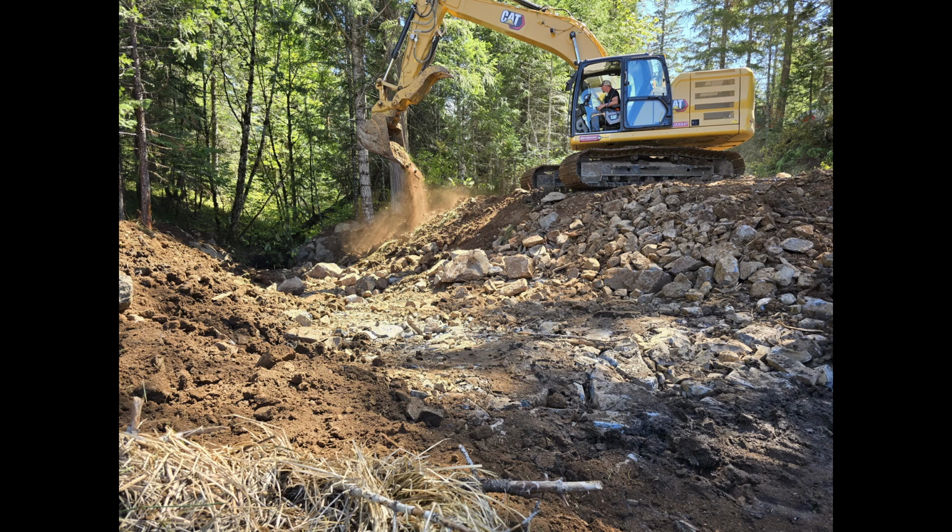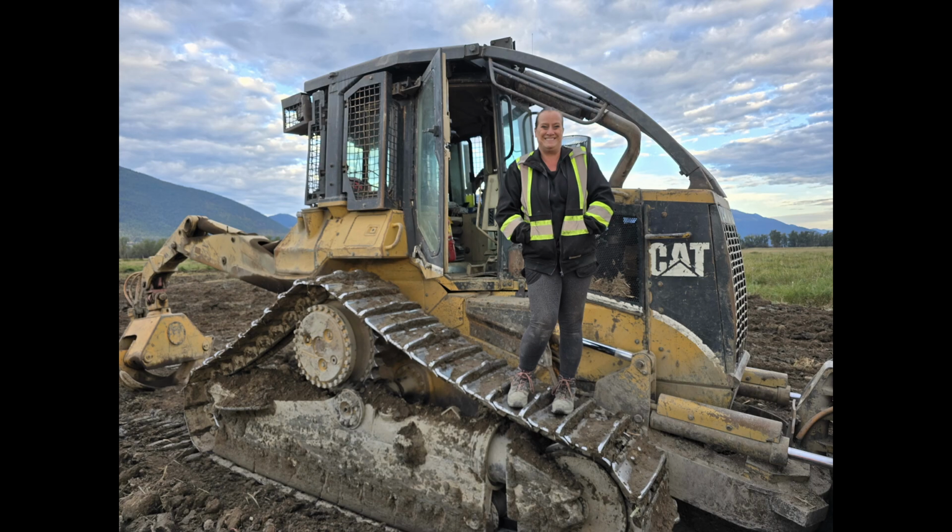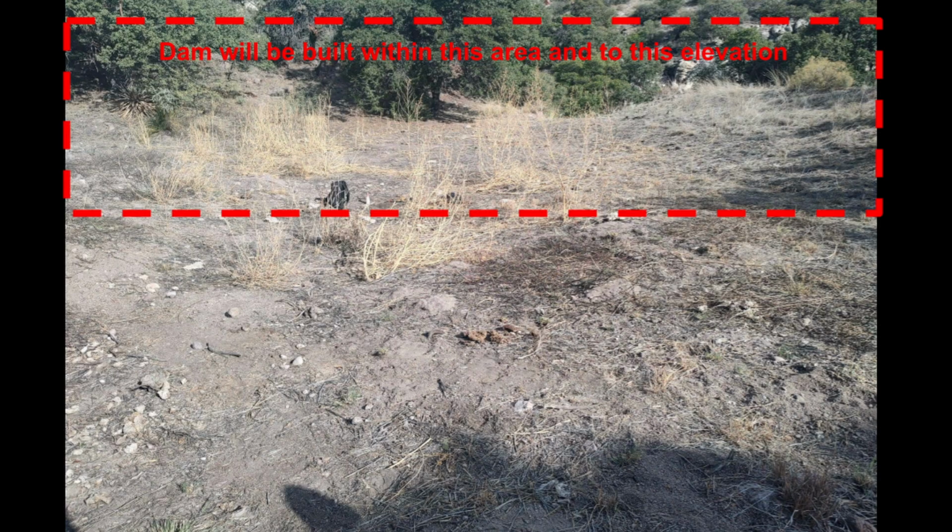An excavator with an operator will be needed to cut through the ridge to build the new spillway. A dozer and an operator will be needed to build the new spillway and to repair the dam. The soil removed from digging the new spillway will be used to build a section of dam that blocks the old washed-out spillway and raises the elevation of low places in the dam.